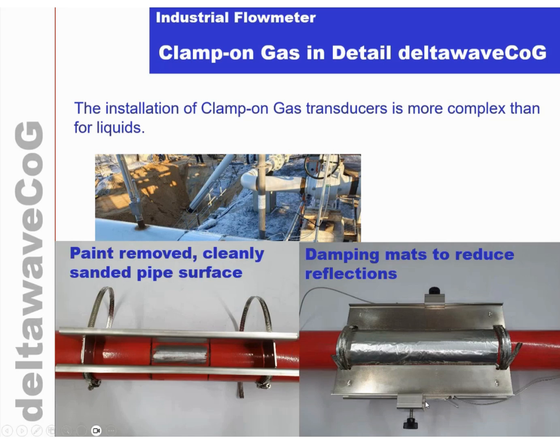So we have the transducers in here. They are firmly attached to the pipe. There is some coupling compound. We have a good surface, so we have prepared everything very well to have an optimum coupling of the signal into the steel pipe. This is necessary for